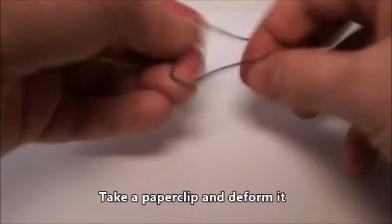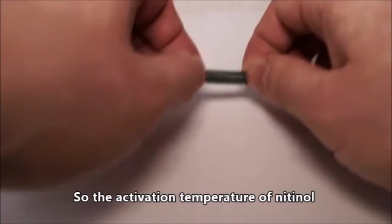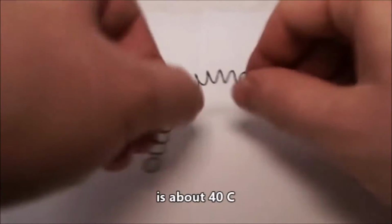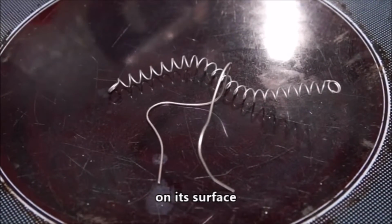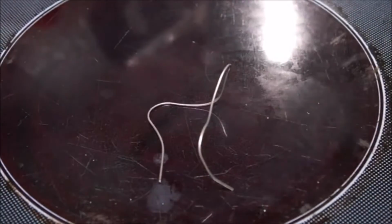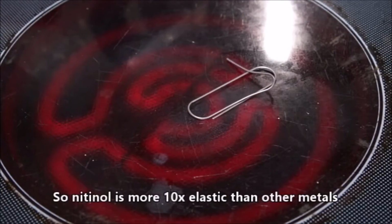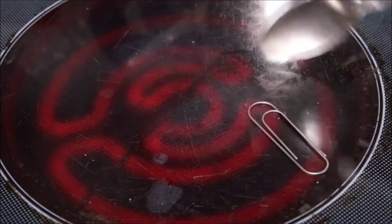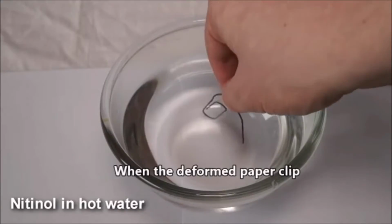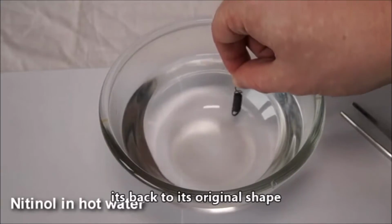Take a paperclip and deform it. After that, take a spring and also deform it. The activation temperature of nitinol is about 40 degrees Celsius. The stove is heated, and then put the deformed paperclip on its surface. When it's heated, it goes back to its original shape. Nitinol is 10 times more elastic than other metals. This is an example of nitinol in hot water. When the deformed paperclip and spring are put in the hot water, they go back to their original shape.